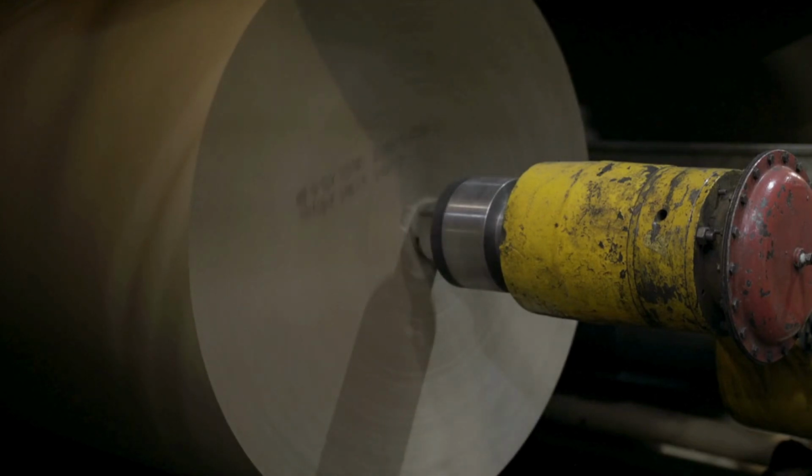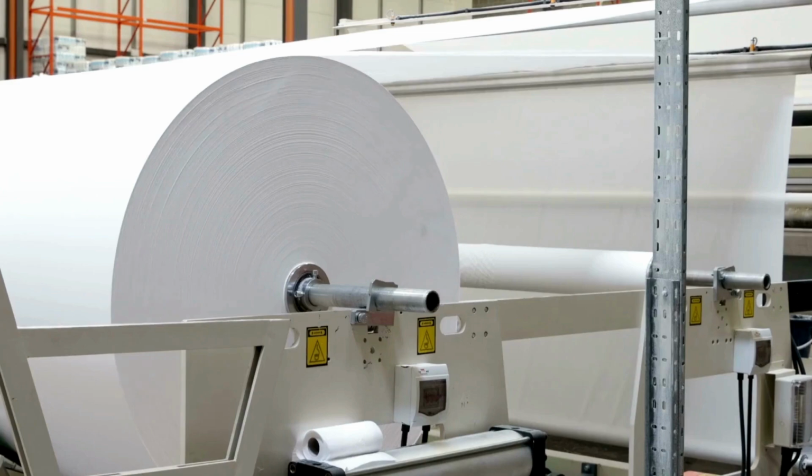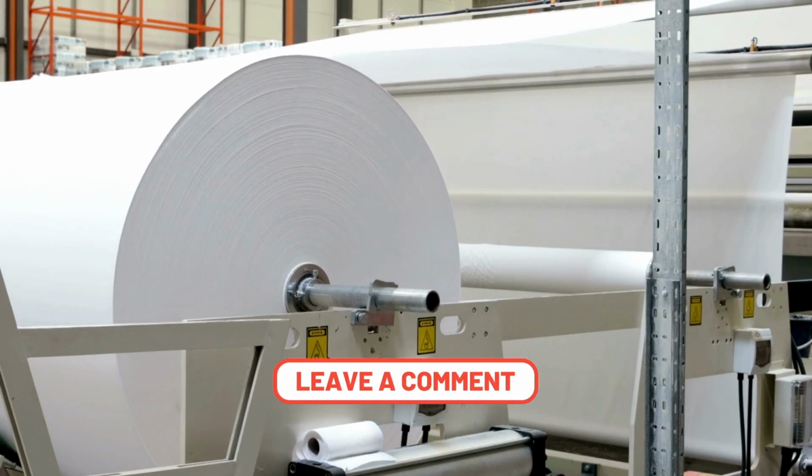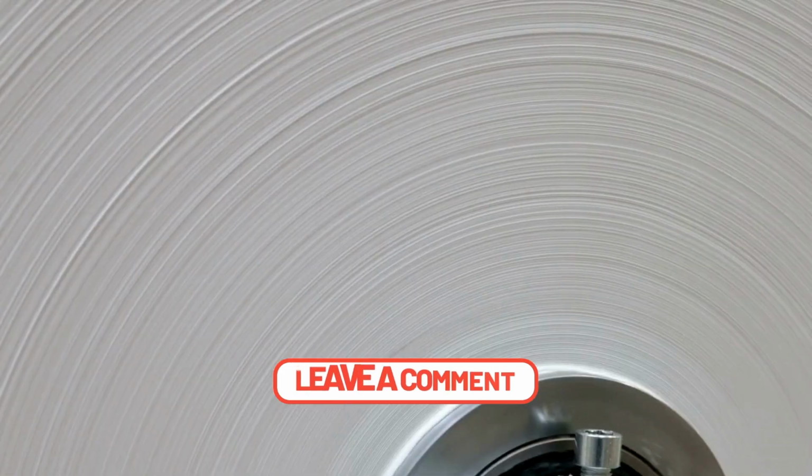In the sizing and coating step, which is an optional step, a thin layer of sizing agents, such as starch or resin, is applied to the paper to enhance surface properties like smoothness, strength, and printability. Some papers are coated with additional layers to create finishes like gloss or matte.